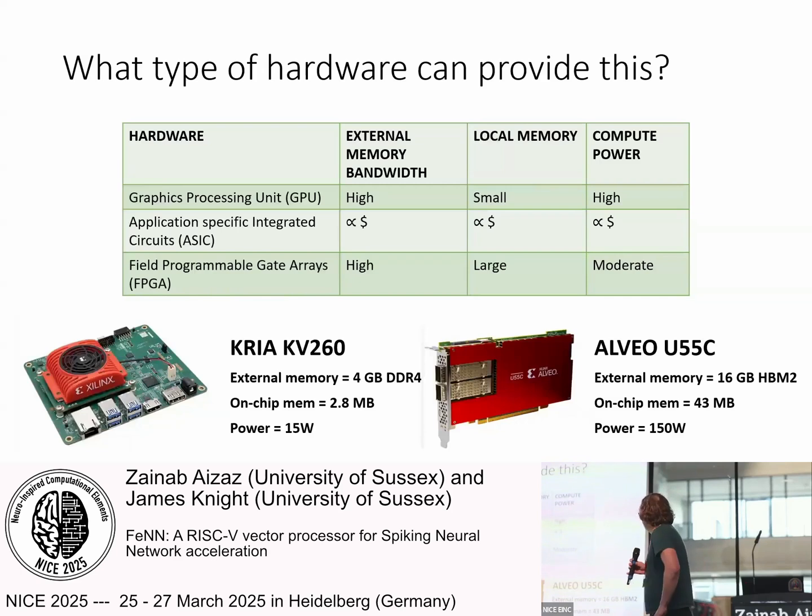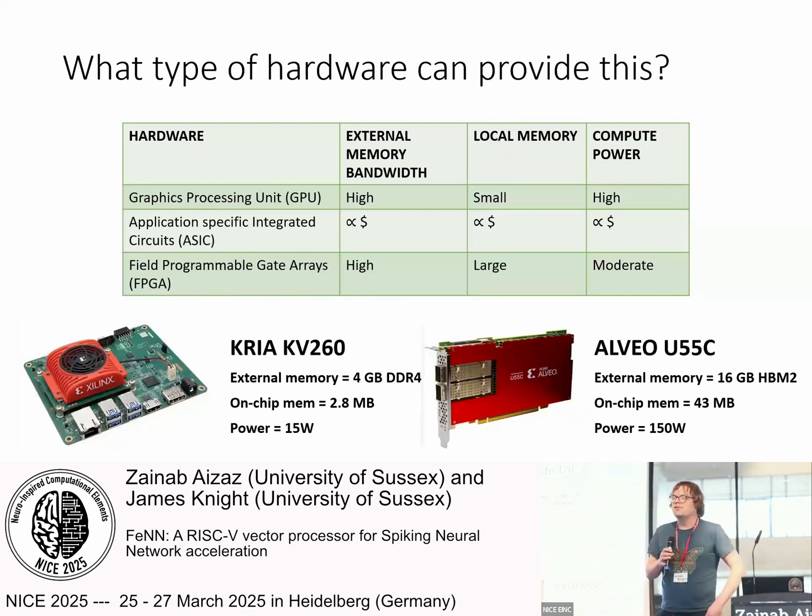And then if we go up the spectrum, you get this thing called an Alveo system, which is sort of a V100 alternative. This has got 60 gig of high bandwidth memory and 40 odd meg of on-chip memory. So it's more than you get on an equivalent GPU, and it's not cache, it's programmable, user-controlled scratchpad memory. So both of these things are kind of in-memory accelerators as well, which I think is something that's underlooked at in the neuromorphic community. Having an in-memory accelerator is really nice as you integrate with applications much more easily. So they're inherently potentially easier to use, easier to integrate.